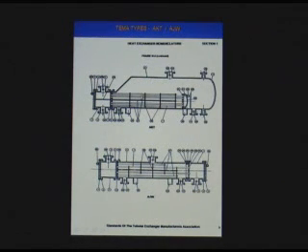This is called a kettle type reboiler. K stands for kettle. You could have a BKU, an AKU. In this case, this is an AKT, but if you were to make this U-bend tubes down here, get rid of the floating head, then that would be an AKU reboiler.